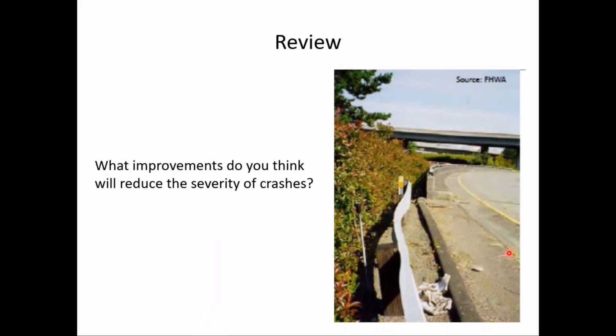Yeah, good response. I think that captures it. The rail needs to be flush with or in front of the curb, and we need a good transition here between the semi-rigid device, the W-beam, and the concrete rail. So thank you all for that.